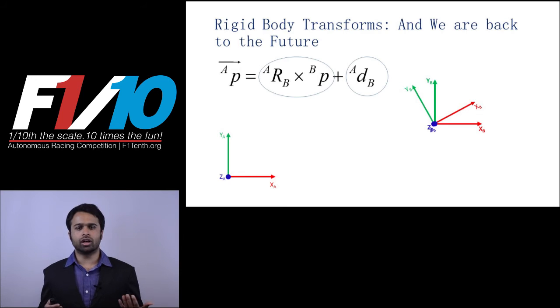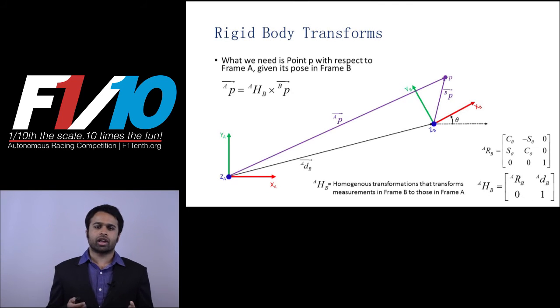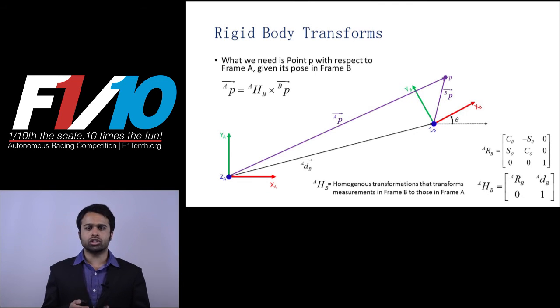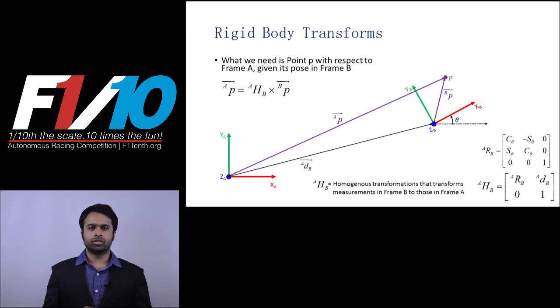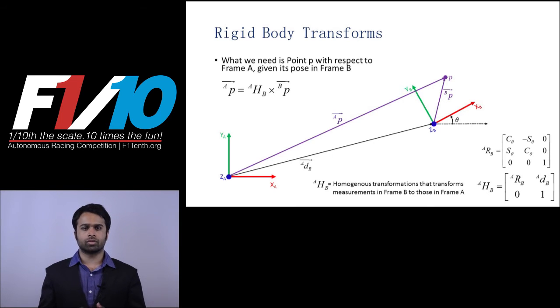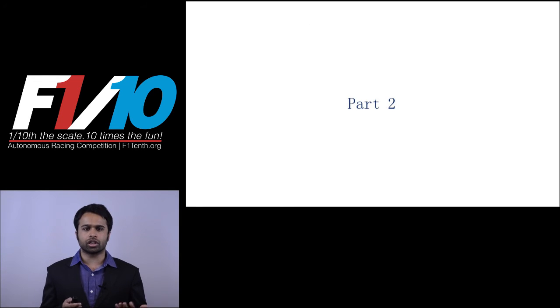So what we have eventually done is rotate the frame and then translate the frame. We can now compensate for any rotation or translation between frames. On simplifying the previous equation, we obtain the homogeneous transformation matrix H, which is represented as shown. This was the theory and importance of rigid body transformations in robotic systems. We will now look at some implementation details in regards to some conventions, ROS and our system. Now we'll be going into some implementation details, conventions and debugging tools that ROS provides.